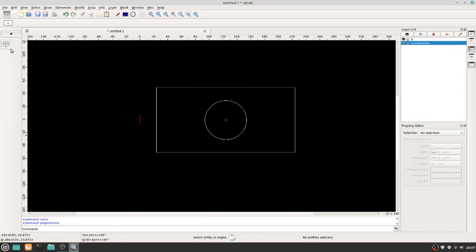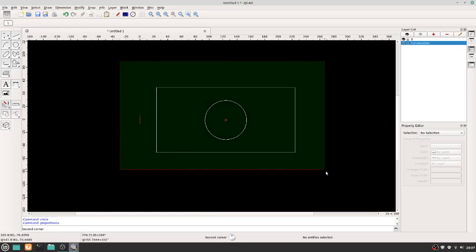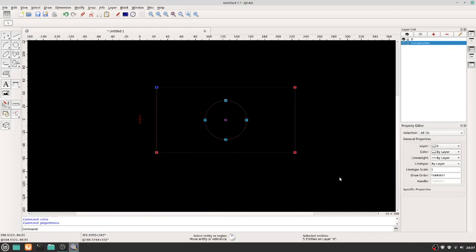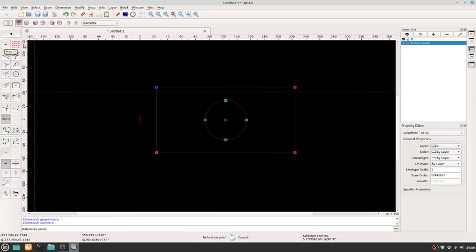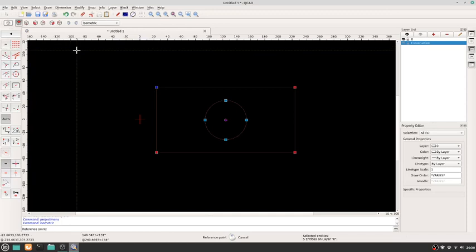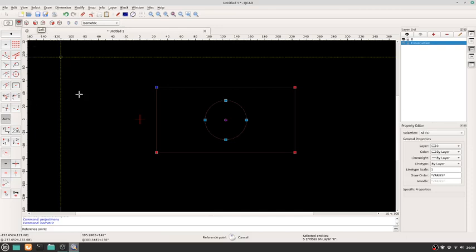You can actually click on a tool here. So if I select all of this, if I hold my left mouse button and draw a box and select everything here and let go, as you can see, if I click on this tool here, projection tools, and I click on isometric projection, you can actually select where you want to project your isometric view, whether it's on the XY axis or XZ, what plane you want it on.